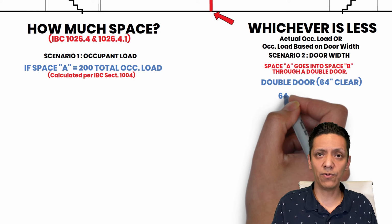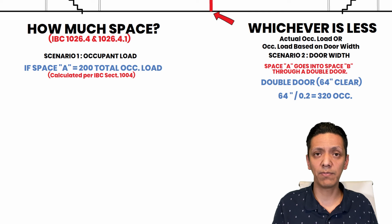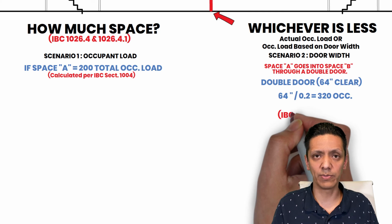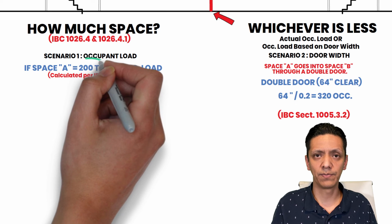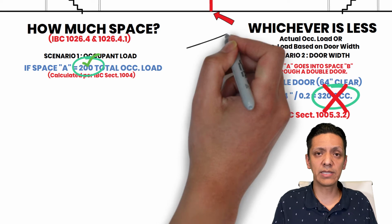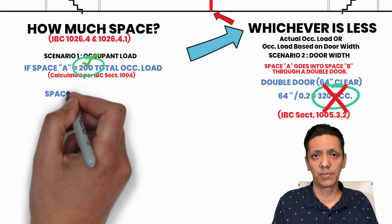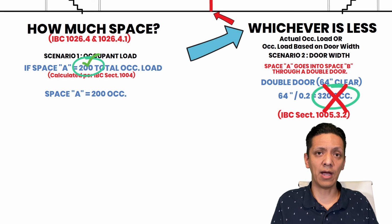Then we take 64 inches, we divide it by 0.2, and we come up with 320 occupants. And this is done per IBC section 1005.3.2. So in this example, scenario 1 wins because it's the least amount of occupants. And so we can assume that space A is going to have 200 occupants exiting into space B.